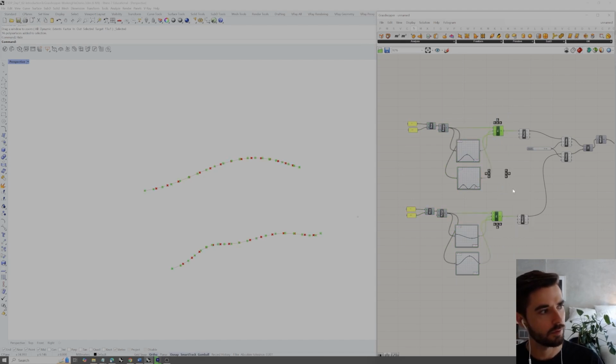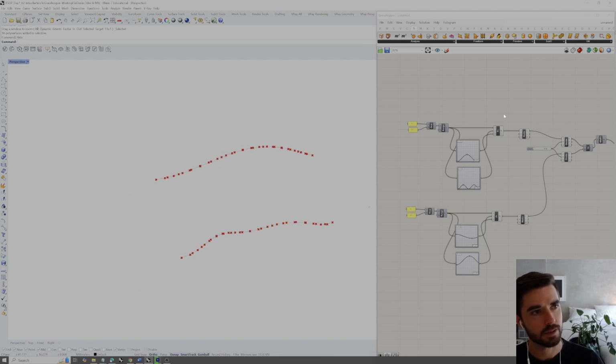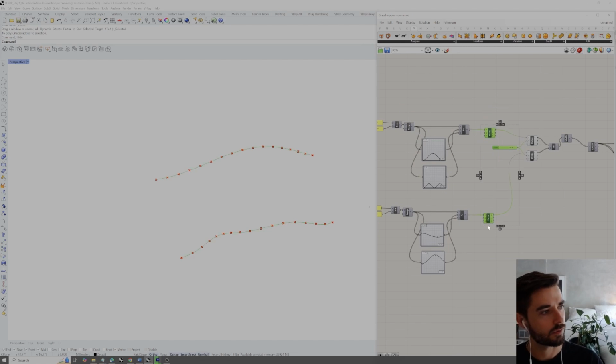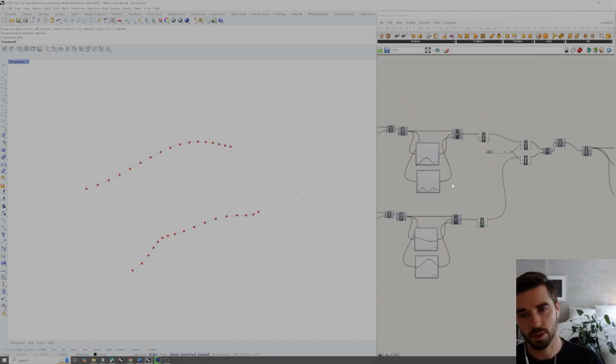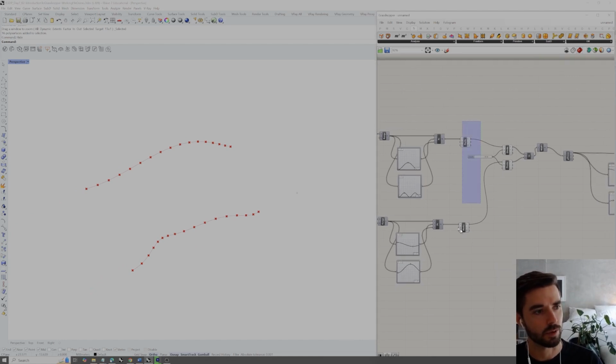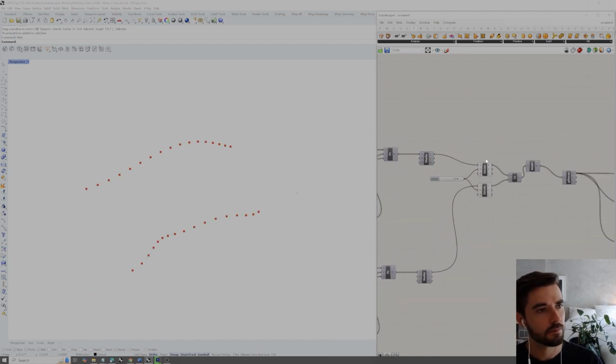So if I preview these, we can see that that's the original point set drawn out in space, which we then have built curves from. So we draw curves through that set of points using the graph mapper to parametrically control them. And if I hide this curve, or these curves, we then have divisions drawn across those curves into equidistant segments,